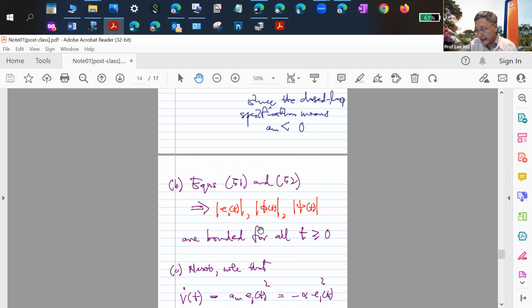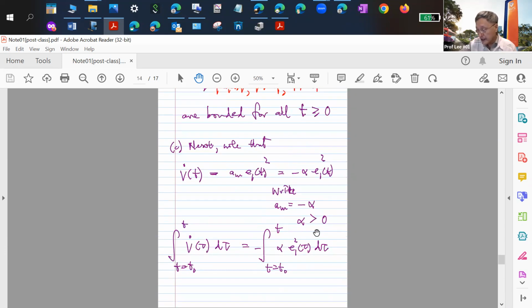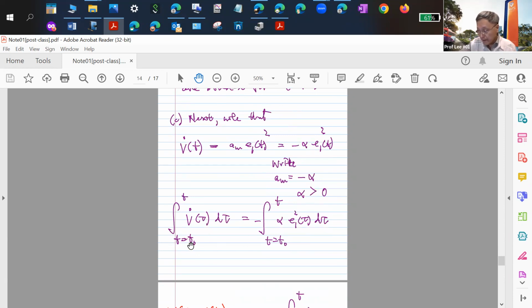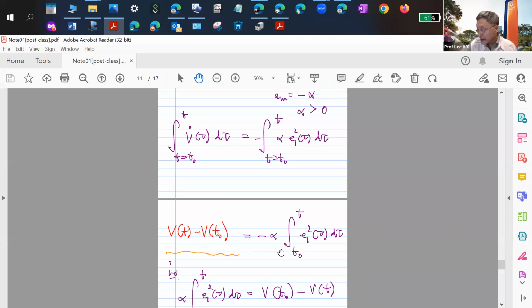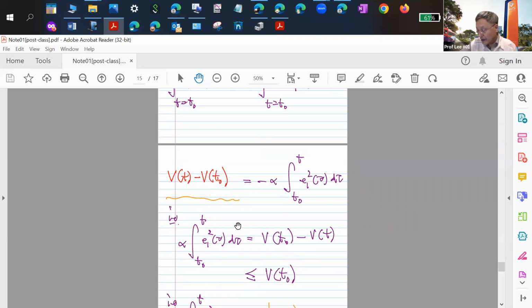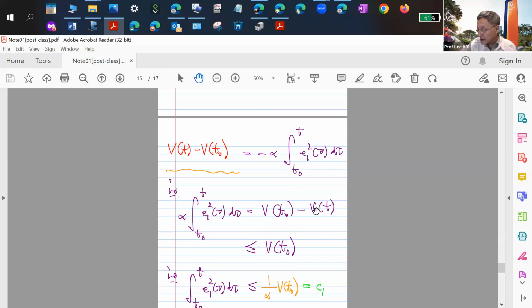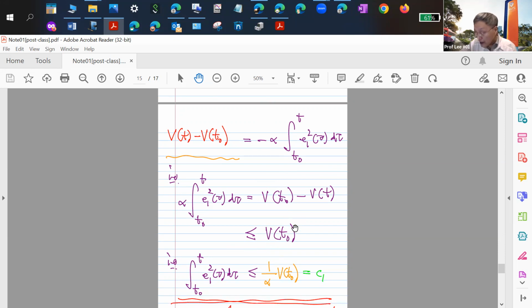We take the V dot signal, and now we take its definite integral from 6:15 last week to any time. Anytime. We started at 6:15, so we can let it continue the whole week up to now. So we integrate up to now, and even if you integrate up to now from last week 6:15, it will obey this relationship. As we said, we simplify that because V(t) is a positive number. So if we remove this, we take a more conservative overbound: it is less than or equal to V(t0), which is the number at 6:15 when we started last week.